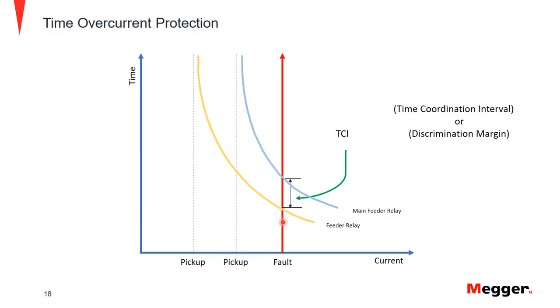So the safety margin is to calculate for safety margins within different devices can play a role as well with calculations. Relay tap selections. So let's say you have a microprocessor relay on one breaker, and then the second breaker downstream is actually an electromechanical relay. So you're going to have a little bit of an error there as well. The relay operate times. Some relays operate faster than others, especially if you don't have the same brand or same type of relay in series. And also you have CT ratio errors as well that do play a role in this.